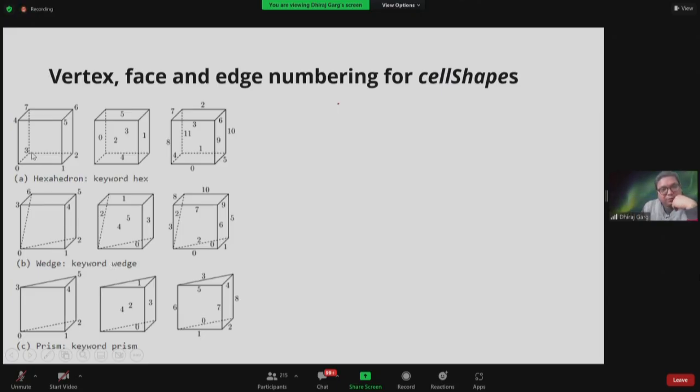So for example, you merge 3 with 0. So you can create a wedge type. So what will be the thing? Basically here 0, 1, 2, and 0, because 3 is now merged as 0. And then this is the lower face, and the top face should be then 3, 4, 5, 6, because now there are only 7 points.